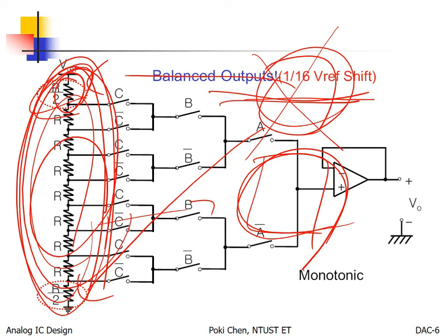So the most fundamental idea for matching layout is to apply unit devices. Everybody needs to be composed of exactly the same sub-devices. That's your first step. But for real implementation, you can say, oh, 2 here, 1, 1, 1, 1, 2. No, it's still no good. Why?